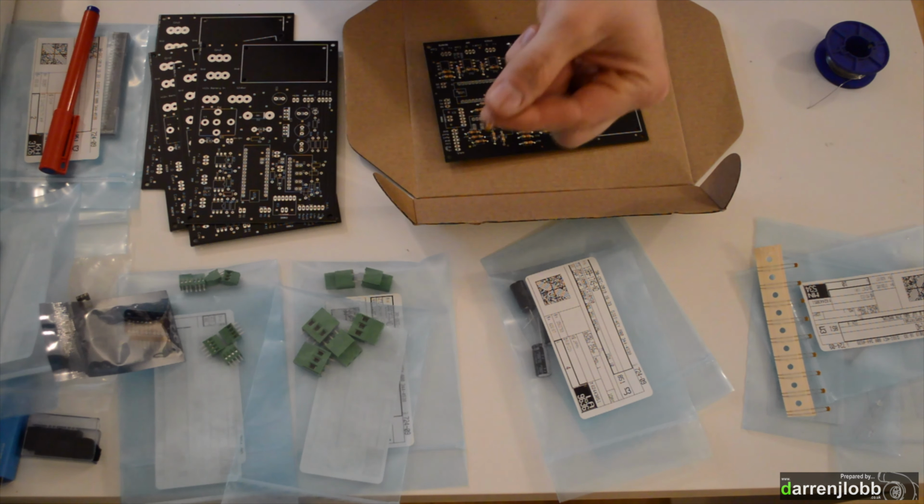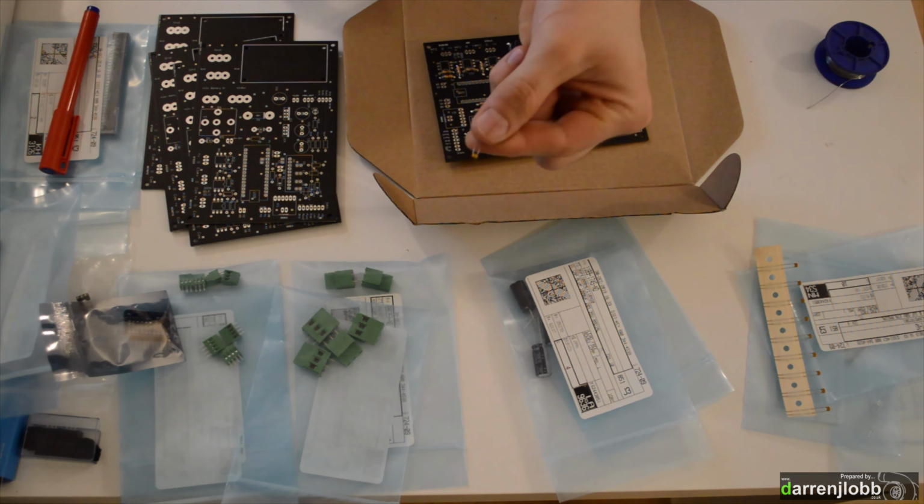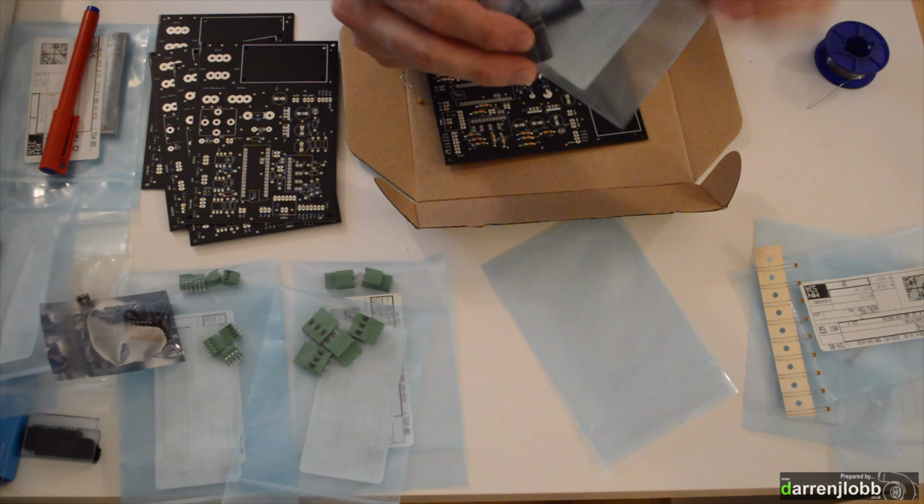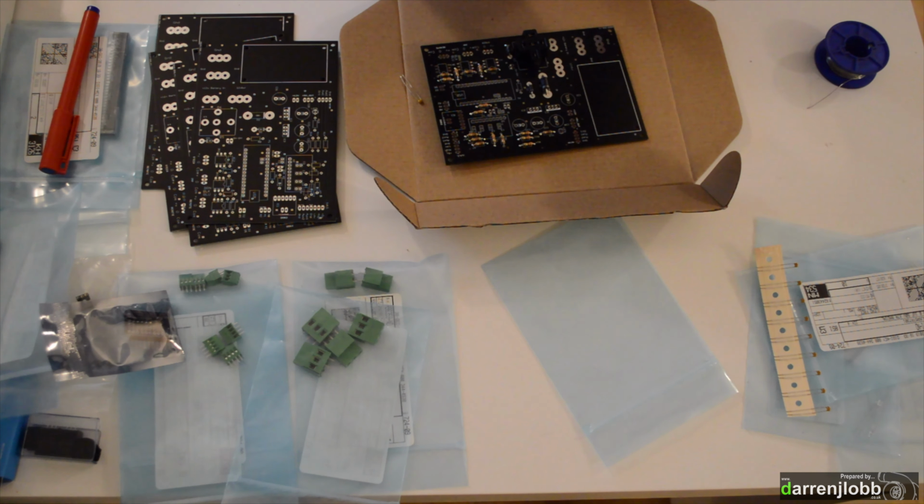These smaller ceramic style capacitors, the polarity doesn't matter, so same as resistors, they can go either way round. The electrolytic ones, the bigger round ones, it does matter on them. You'll notice they've got different length legs, and also a white stripe on the side of them. The shorter leg on the white stripe side is the negative side, which is indicated on the board with the white stripe.